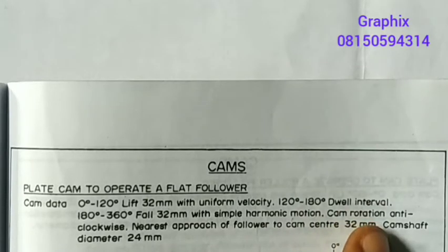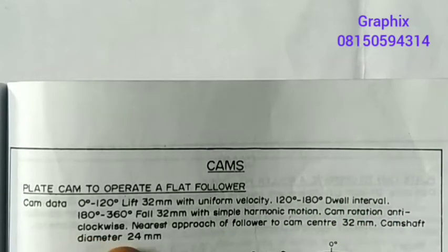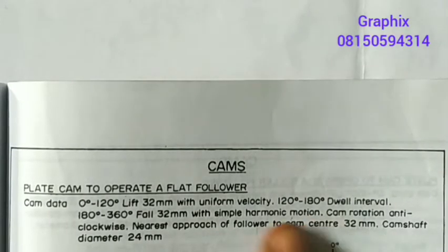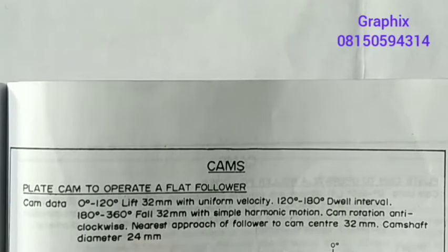The cam rotation is anti-clockwise. Nearest approach of the follower to the cam center is 32 millimeter. Camshaft diameter is 24 millimeter.